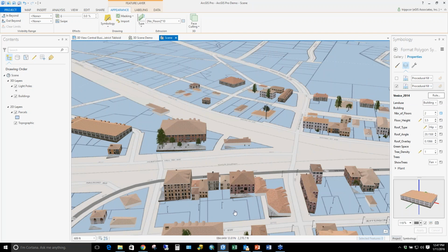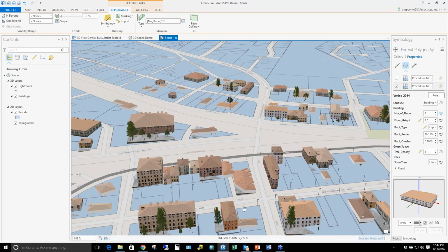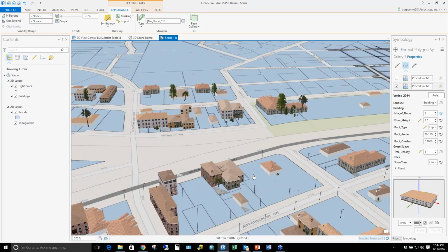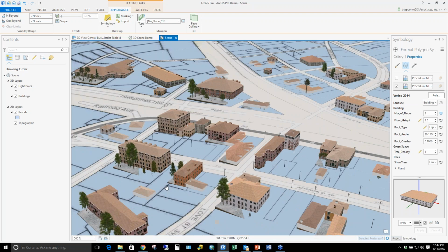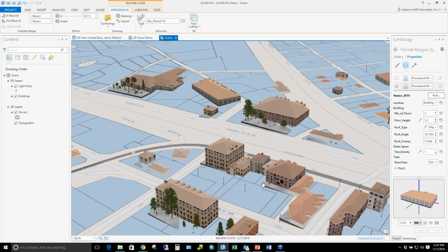Yes and no. To make a virtual walkthrough video, you can do what they call a roam. If I click the Q button and move my mouse, I can do a fly through. So if you have some video recording app on your computer, you could record that.